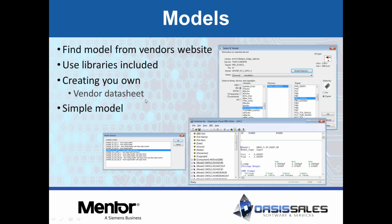The tool you may be using would have an application inside of it that allows you to create a model, either just for a single pin or for an entire component you can use in your design. So doing something even with an estimated rising and falling edge and a receiver end is better than doing nothing at all.